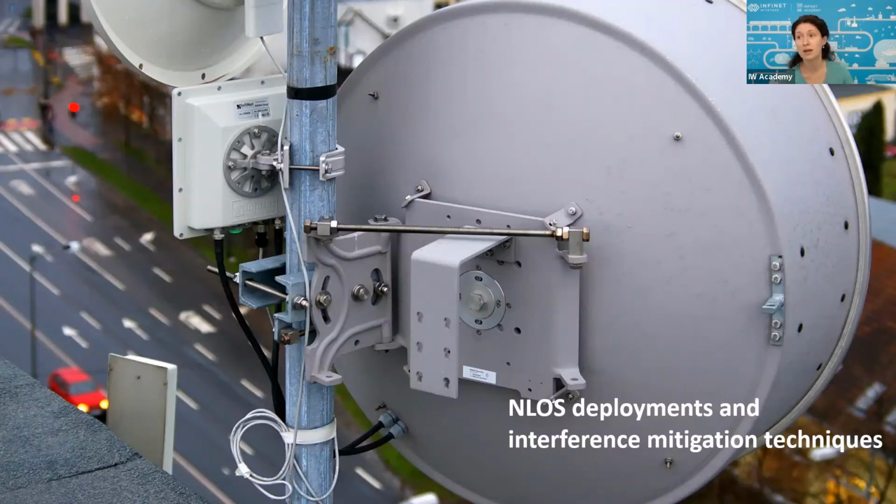Other systems may have automatic transmit power control, and if they detect that your power is increased, they will automatically increase their power also and will interfere with your system as well. So you can try to put the maximum allowed power, but you should see if you have consequences or not, because other systems operating in the area might increase their power as well automatically if they detect your signal.